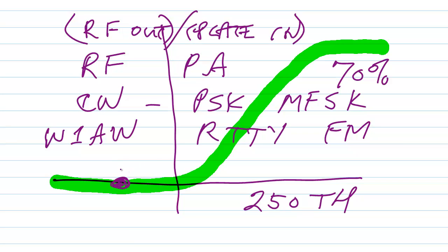So if you are able to operate an amplifier in Class C, go ahead and do it. The only thing is that you will need a lot of driving power in order to make it work. You need a significant drive to make a Class C amplifier function properly.